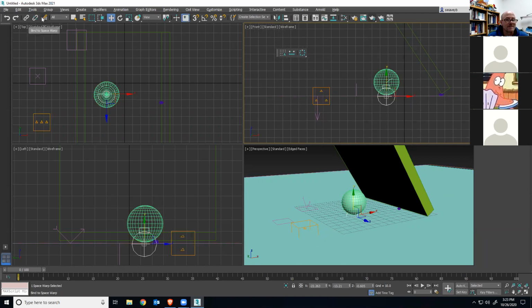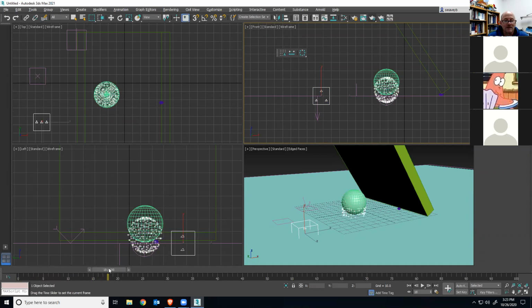All right, so let's bind this stuff together. I haven't bound anything to this particle array yet, so let's do that. Once I bind it to the gravity, it's going to fall, so we'll see what that does. So here's the particle array. Drag that to gravity. See them fall? They get created, and then gravity is just pulling them down. That's okay, because I have this bomb going on. So I'm going to drag from there to the bomb.